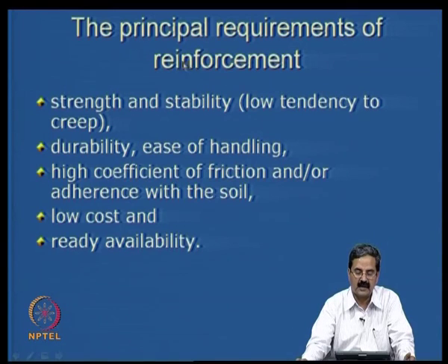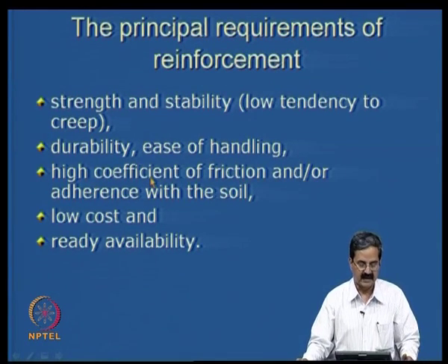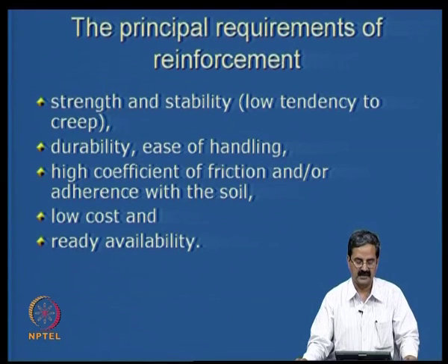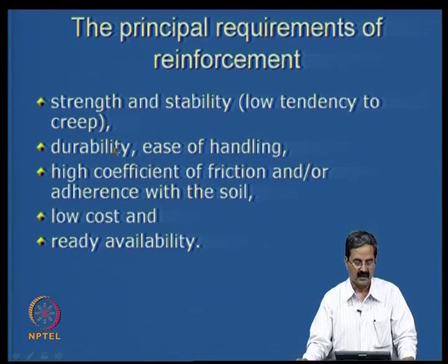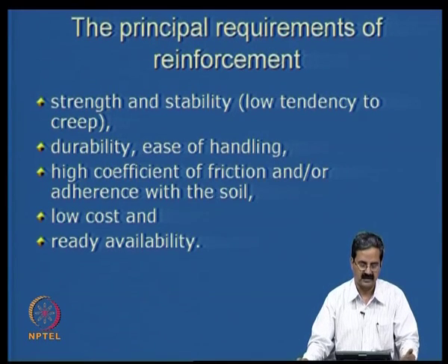What are the principal requirements of the reinforcement? We have seen the strength of the reinforcement; in fact, we did calculations on slope stability and other things. Strength of the geotextile or the geogrid is important, and its stability, like it should not creep too much. Of course, the polymeric materials do creep, so strength and stability are important. Then durability, like how long, because you are trying to design for 100 years or 50 years or whatever.